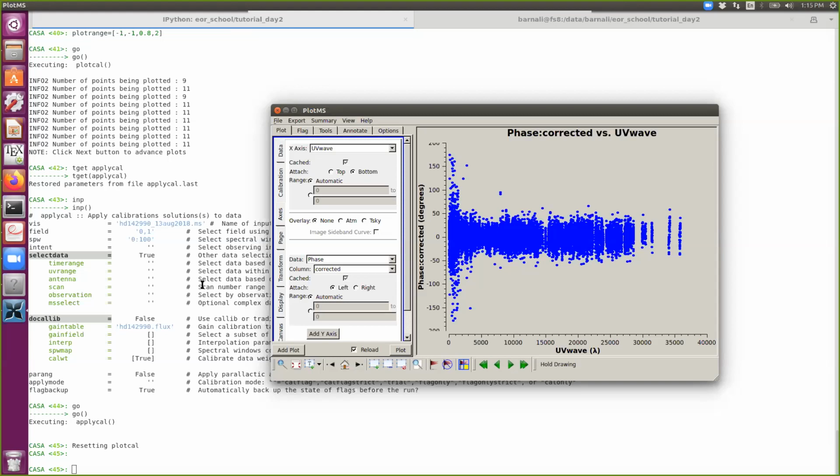And sometimes an antenna may not be working, so it is giving all zeros. That is not RFI, but we also have to take care of that antenna, since it is not receiving any signal from the sky. It can also be a satellite which happens to be there for 5 minutes of your observation, radiating to all the antennas in your array. So all those 5 minutes of data are gone.